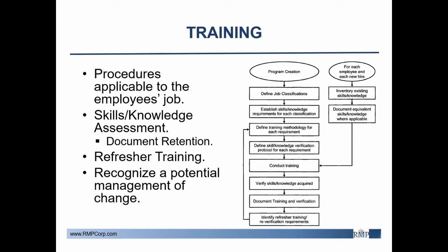To develop a training program, you can perform a review of the MI program's components, such as inspection, testing, and preventative maintenance plans, quality assurance, and common repair activities. Then develop a list of job classifications for the personnel who will perform the tasks. Solicit input from your experienced, knowledgeable personnel, and assemble a list of the skills and knowledge required within each